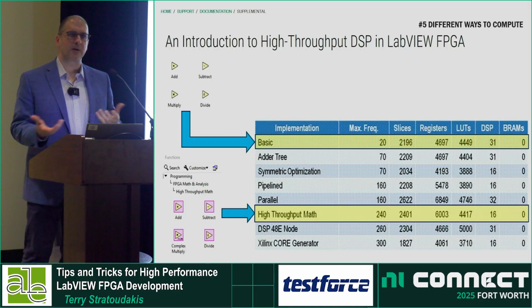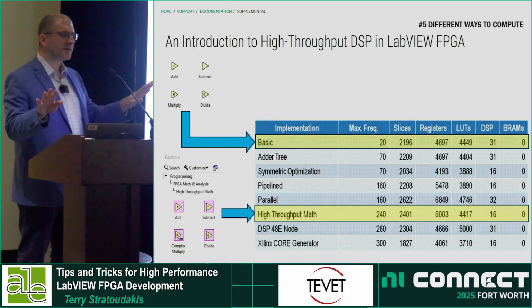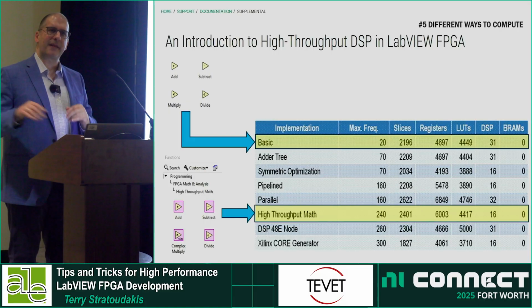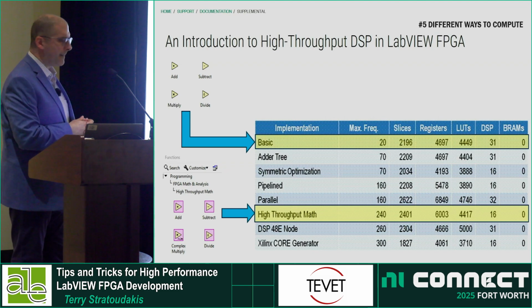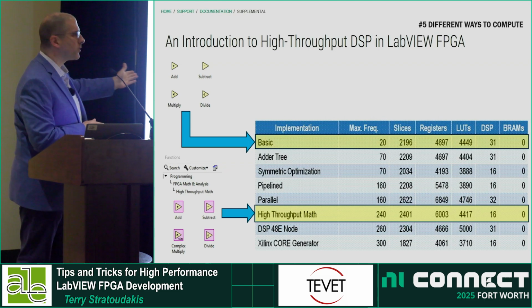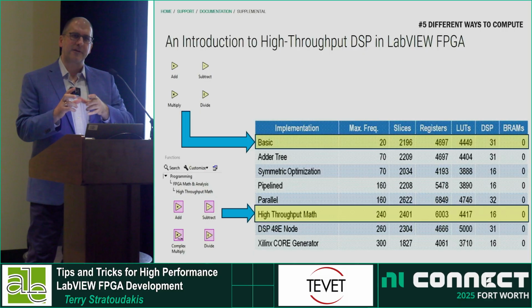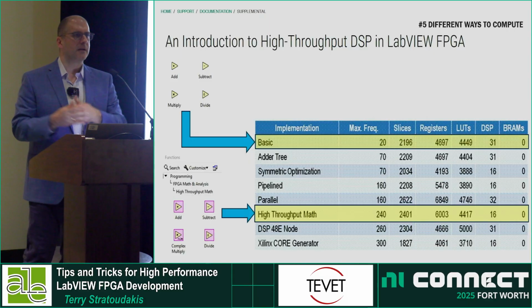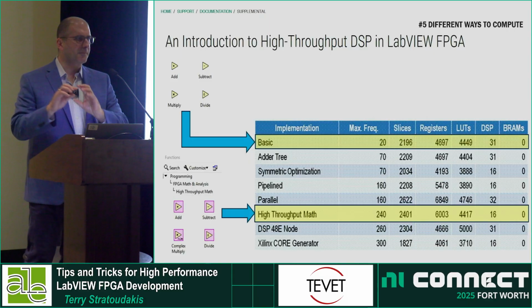First of all, they may be very complex to use. If you don't need to go at that rate, we don't need to have that extra effort on the project. If 20 megahertz is enough, it's enough. I could say, for example, the Xilinx core generator is very specific, right? That filter may need to be modified because it has very specific configuration settings, and maybe you won't be able to get exactly the type of filter you need, or maybe there's something you need to change.